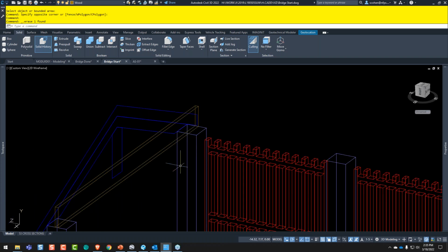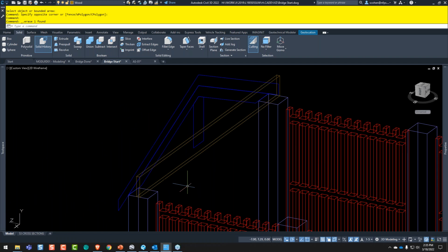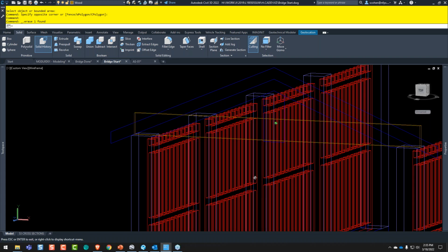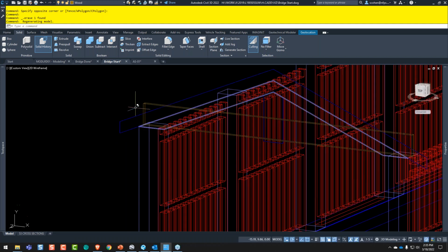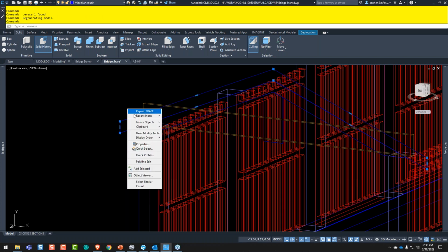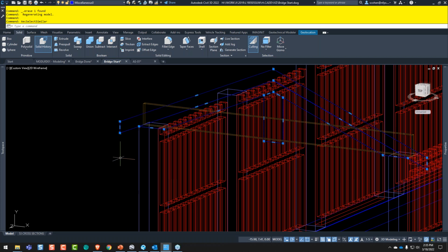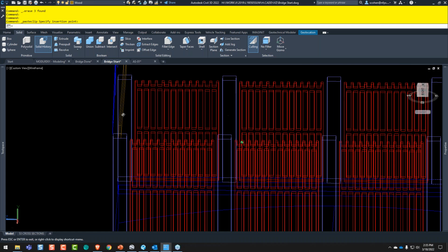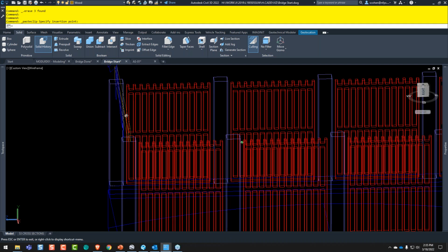Then of course I would just copy that around, same exact thing, right? Now again, for the 2 by 4s, wherever they need to sit, if let's say one's up here, I would move that up to the top. Or actually, that was the right point. I guess I should have just left it. I didn't realize that. I think it's still on my clipboard. Let's delete those. If I do a Control-V, there we go, and snap here, right? Now it's in the right spot. Okay, so I would do the same thing with the 2 by 4, and then I would just array it all the way across.